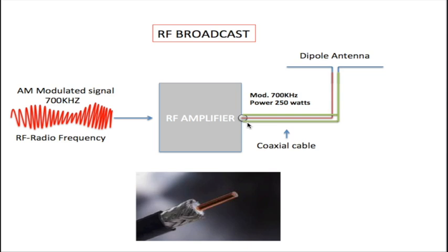If you don't have impedance matching between the RF amplifier and the coaxial cable, you wouldn't have all of this power being radiated out on the antenna. You will have part of it being reflected back towards the RF amplifier, and this is what they call a standing wave. Power being reflected back, and you still have power being sent out from the amplifier. The two meet and you have a wave in here, and this could actually damage the cable, and under extreme conditions it could also damage the RF amplifier as well.